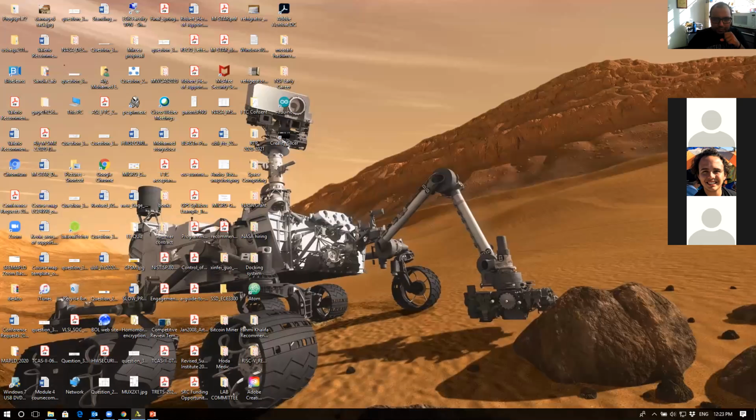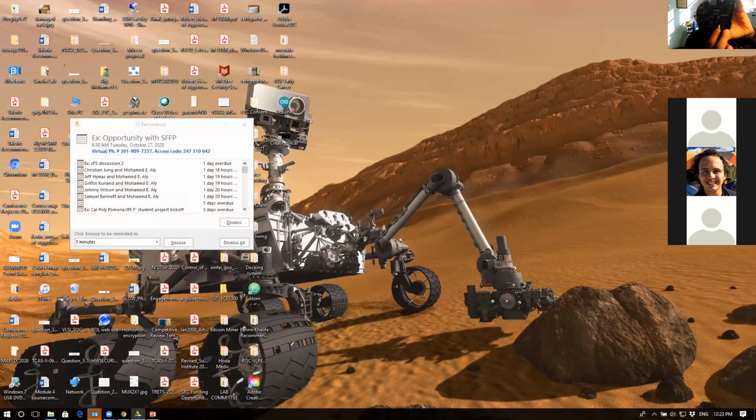Okay, anyway, if we look at this, I need RGB also because these 3 LEDs we have, they have colors, right? We have 2 LEDs here. Can you see my camera? These 2. Everybody can see it, right? Yes. These 2 actually have 3 different colors. So you can have 3 different PWM cores, and each will be responsible for a color, and you play with the resolution, then you will mix a color. You know what I mean? That's one of the possible ways to do it.